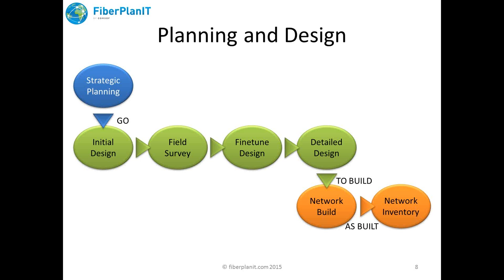And then finally, of course, this to-build plan is a basis for the network that is really constructed in the field. And obviously in the construction, if there is any change, it's also important to capture that in your documentation. So there you need to document the as-built network so that you know exactly where the cables and all the components are geographically located. So this is an example and a summary of a full planning and design process.